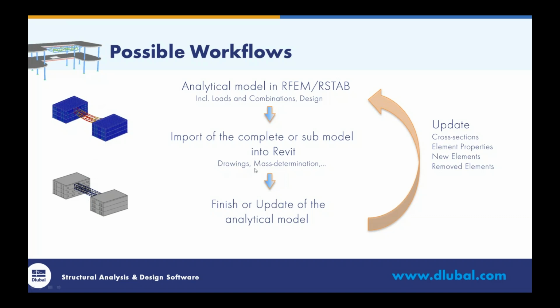In Revit, you can, again, create these drawings and make whatever you do in Revit. And even if you make some changes there, you can update the RFEM model based on the changes you've made in Revit. So again, you have the full cycle, but this time you started with RFEM and not with Revit.